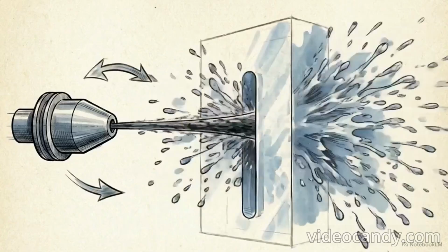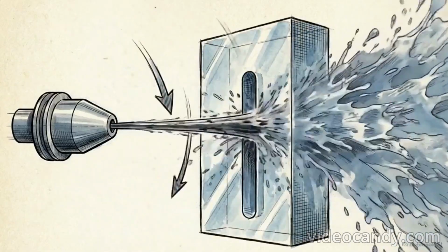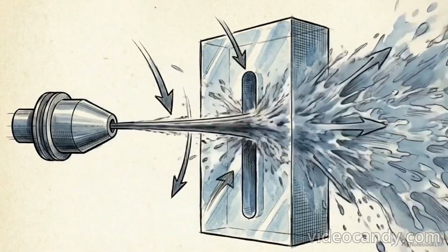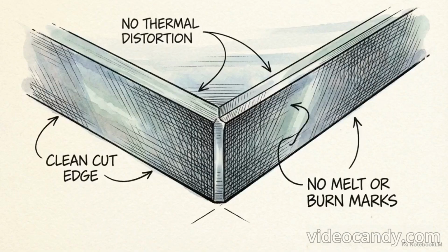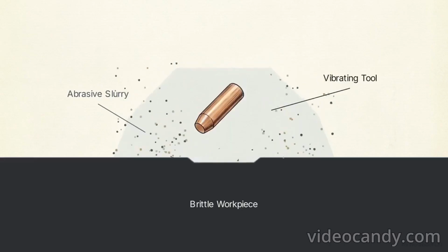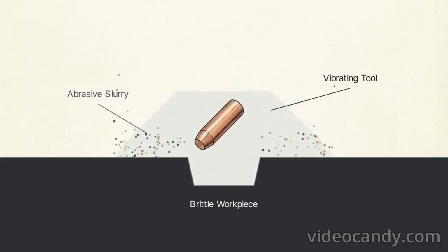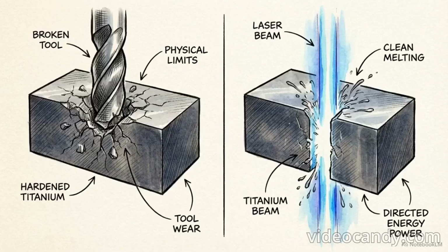Another major thermal method is laser beam machining, or LBM. This process focuses a high-intensity beam of coherent light to rapidly melt or ablate complex profiles, most often used on flat sheet metal. For materials that cannot survive extreme heat, engineers use water jet machining. This method fires a hypervelocity stream of water mixed with abrasives to cleanly and precisely slice through heat-sensitive targets.